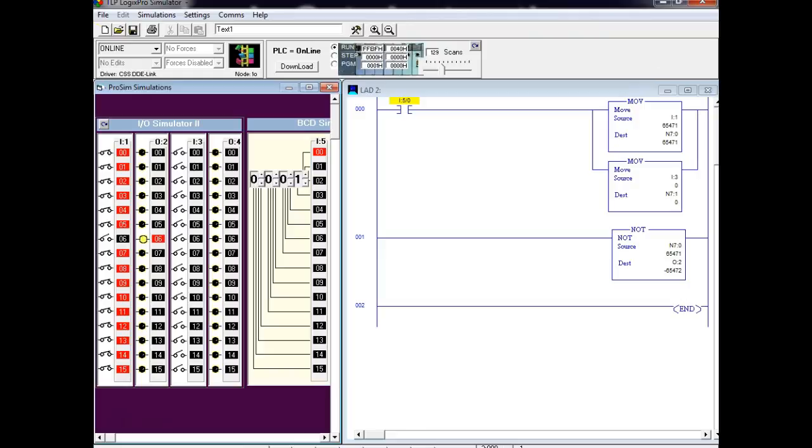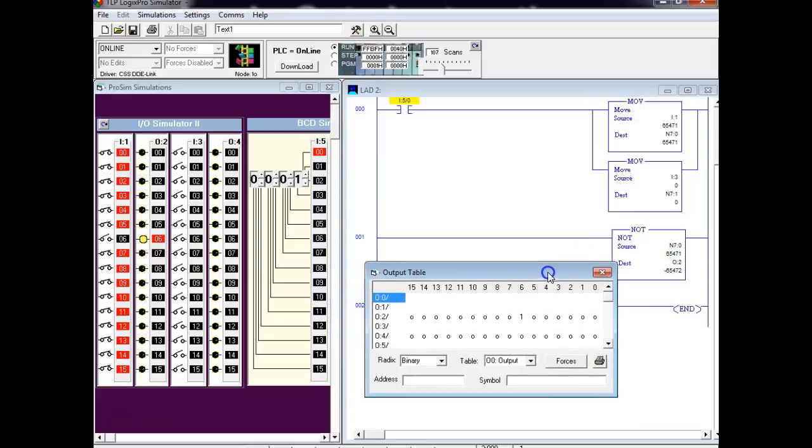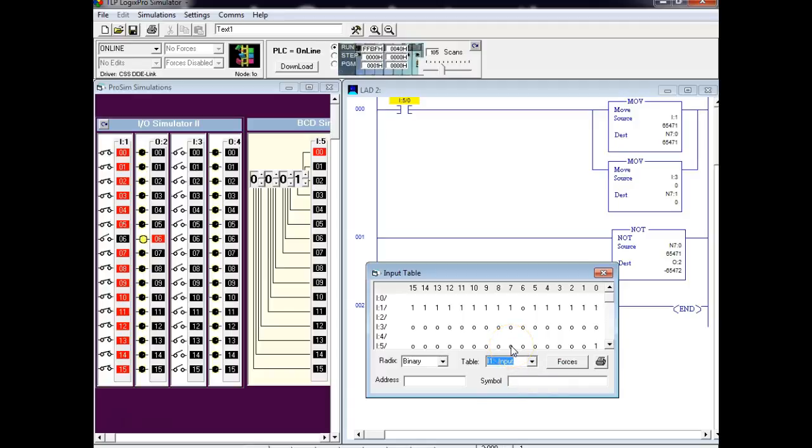Okay. So here I'm getting a 1. If I look at the registers, on this one, by the way, you can hit this up here. What we're doing is we're looking at my outputs. But now let's go back and look at my inputs. Hit 1 and 3 at the same time. Input 3. We're not using 3 for our NOT. We can't use 3. NOT only works with one 16-bit word.